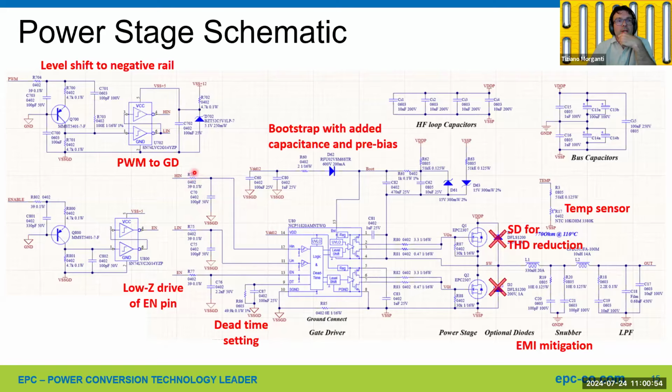So it's just adding a diode here on the discharging path and here. And then we need to bring an additional signal to short the dead time input of the gate driver to ground, because with this gate driver, when you pull down this dead time setting pin below 0.5 volt, it's entering a mode that is using the externally set dead time. So this is pretty easy to do. It's few components added, and I believe it will provide big improvement in terms of efficiency and also in terms of THD at higher power.